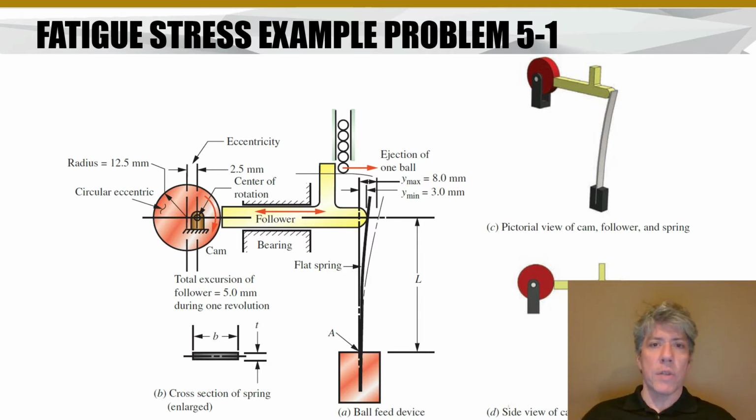And if you think about the stress at the root of that cantilevered beam, well, there's a stress that's applied and then relieved. Now, maybe the spring is always under some stress. Maybe it's always bent to the side a little bit. In that case, the stress is never fully relieved. But this is the setup for the example problem. And I think, if I remember right, he did set it up so the stress is never relieved. And so the maximum and the minimum stresses, well, it depends on which side you look at, right? Because on the right-hand side of this beam, they are what? Compressive stresses. On the left-hand side, they're tensile stresses. So if you were to expect fatigue failure, you should expect it on the left-hand side because that's where there's tension.